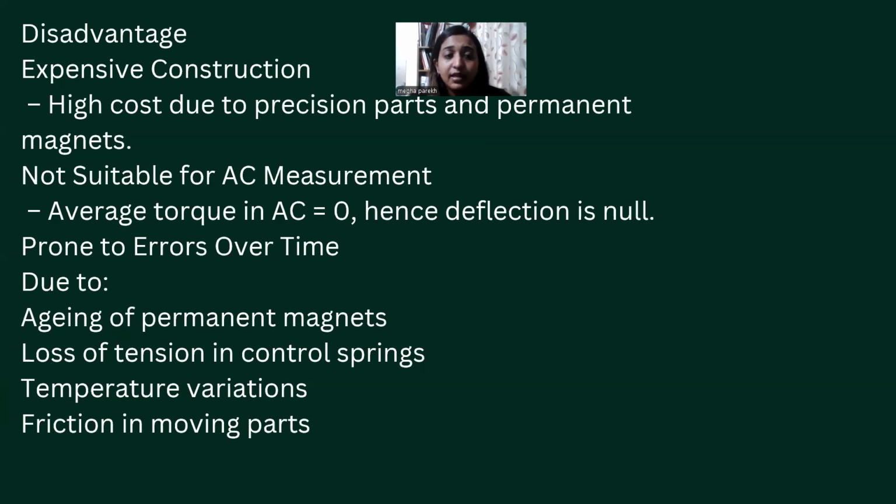It is not suitable for AC measurement. Average torque in AC is equal to 0, hence the deflection is null.